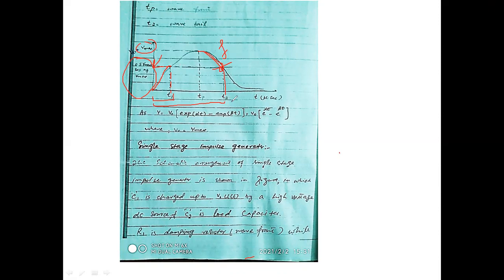The first kind of example of the impulse is the lightning overvoltages, which originate from lightning strokes hitting the phase wires of overhead lines or the bus bar of an outdoor substation. Some substations are indoor and some are outdoor. There is no danger for indoor substations, but there is a high probability of lightning falling on outdoor substation equipment. The amplitudes are very high, usually in the order of 1000 kV.